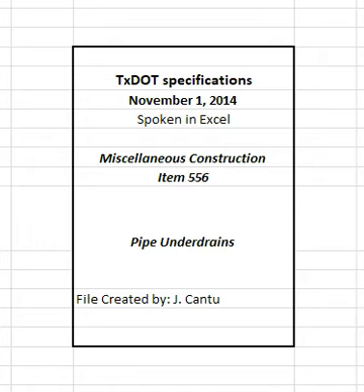2.1.4 Type 4. Bituminous coated corrugated aluminum pipe conforming to the requirements of Type 2 and uniformly coated inside and out with a minimum thickness of 0.05 inches of bituminous material meeting the requirements of Table 1 when tested in accordance with ASTM A849, Material Class A or Material Class BA.